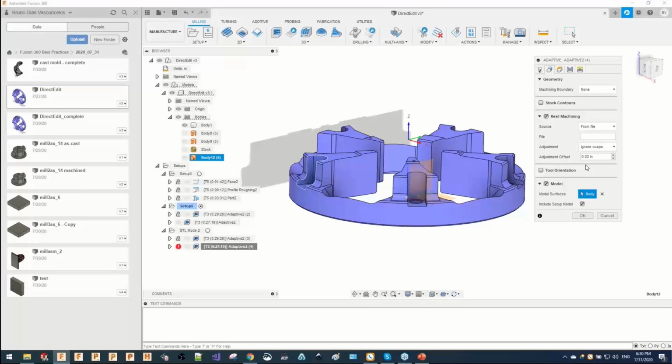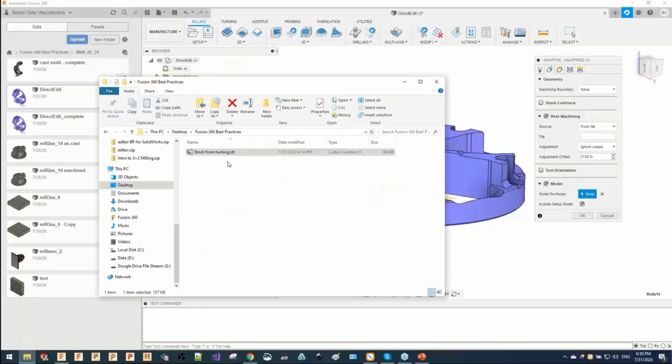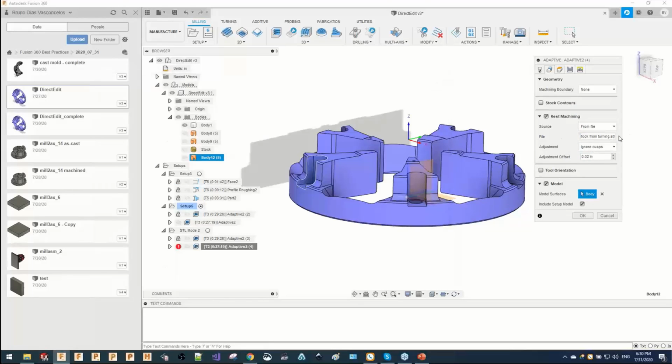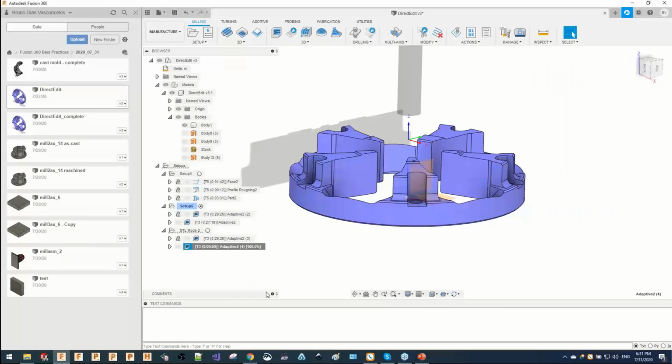I'm not sure why. I have already reported that to the Autodesk development team. But the way you can add the file over here is by drag and drop. Do you see that? Once you drag and drop, the only thing you need to remove is the file prefix and the three slashes, so just keep the path of the STL file without the initial file:///. Remove that and click OK. So this will do exactly the same thing as we did before.